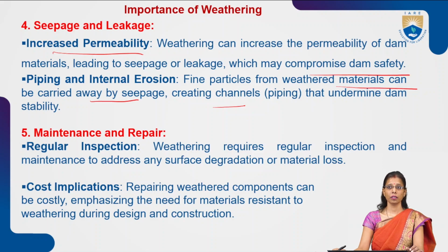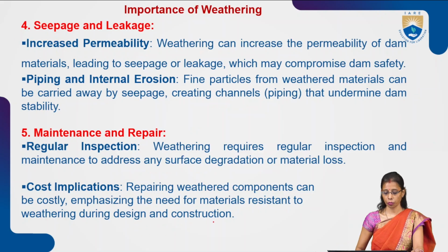Weathering can increase the permeability of dam materials, which means that when the weathering process continues, seepage and cracks may develop in the dams, which may compromise dam safety later on. Now, maintenance and repair. Weathering requires regular inspection and maintenance to address any surface degradation or material loss. When you talk about the cost implication, repairing weathered components can be costly, emphasizing the need for materials resistant to weathering during the design and construction process.